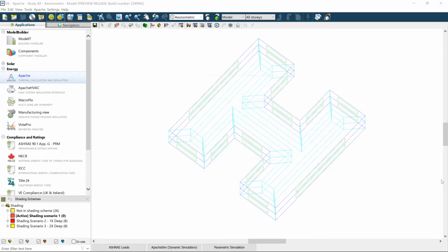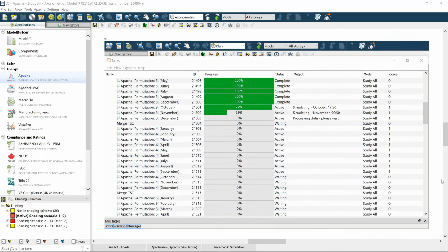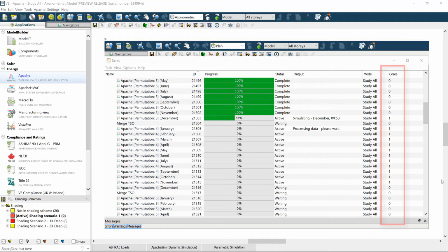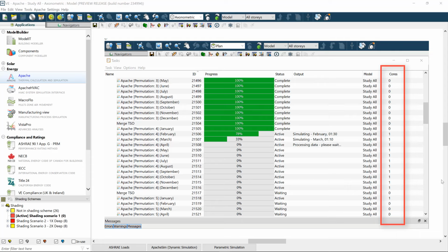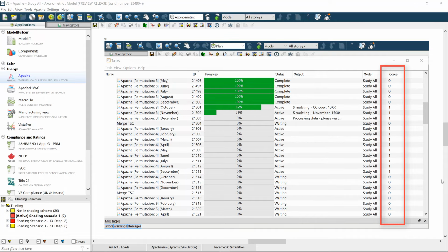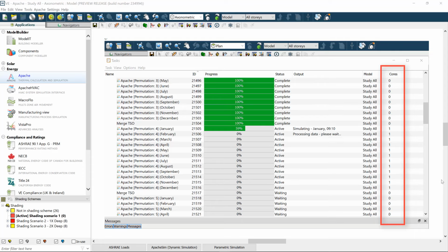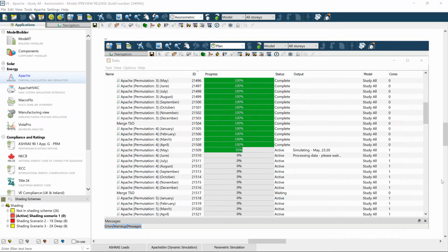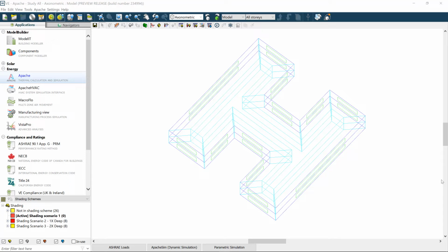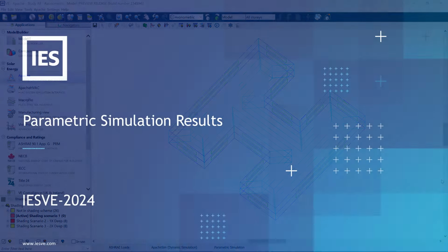For annual simulation, there's more of a hopscotch mechanism at play. All 12 of my logical processors are active, using 4 of them per license seat. When one simulation is done, the processor moves on to the next permutation in the queue. Now, if comparing, say, less than 10 permutations or so, one license seat and up to 4 logical processors should be perfectly fine. However, having multiple seats with multiple logical processors can result in exponential time savings, and even more time is saved if choosing a shortened simulation resolution.